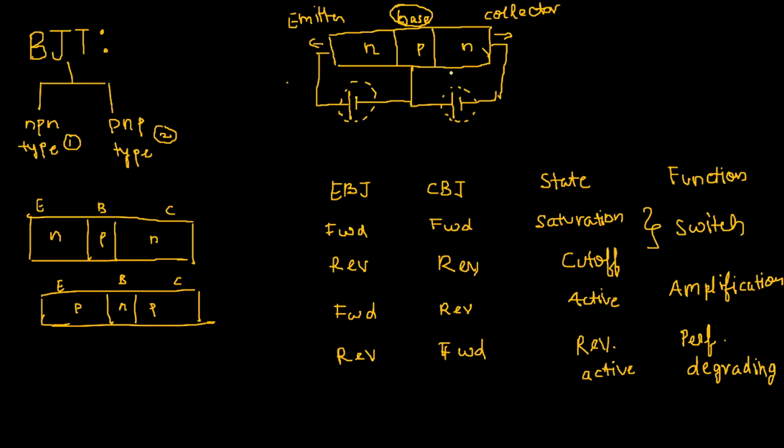But right now, this is all that is needed. The important thing for us here is that the behavior of this particular device changes based on how you bias each part of the transistor. So you can think of the transistor basically as two different PN junction diodes which are almost taped together.